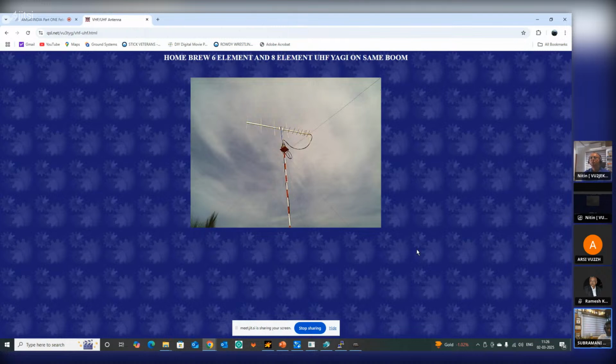But recently IN-SPACe told that we should not distribute it, but absolutely there are no such restrictions as of now that one should not download weather images. So we can receive live weather images from low Earth orbit satellites like NOAA 15, 18, and 19, and also the Russian Meteor M2-3 and M2-4, and also there are a couple of geostationary satellites which transmit beautiful weather images from 36,000 kilometers, the full disk of the Earth. There are a few Korean and Chinese satellites. So we can download even those images from geostationary satellites.